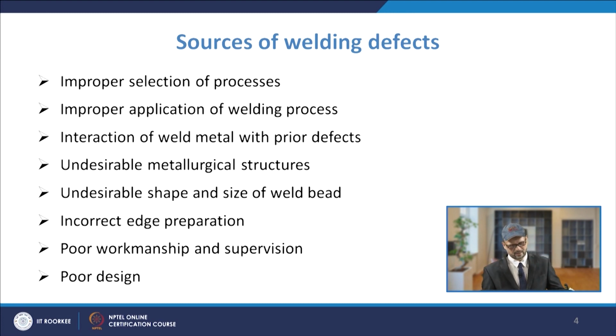So that will lead to many kinds of defects, like there may be lack of fusion because of improper fit up or improper edge preparation. Then you have cracking. Many types of defects originate from incorrect edge preparation. Then you have poor supervision, poor workmanship.